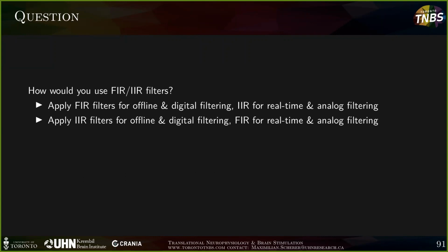As I said, you should ideally use your FIR filter for offline stuff, digital filtering, anything where time is not as much of the essence. And your IIR filter is the ideal solution if you want to do something analog, because you don't want to be sitting there gluing or soldering 10,000 elements onto your circuit.